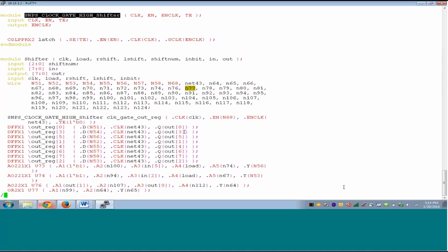So there's a clock gate which is added, and DC is now using an integrated clock gating cell from the library. So even in the default condition, DC sees that your library contains an integrated clock gating cell, ICG, and it has a cell that conforms to the default case. What is the default case? The default case was that it used AND gating with latch.